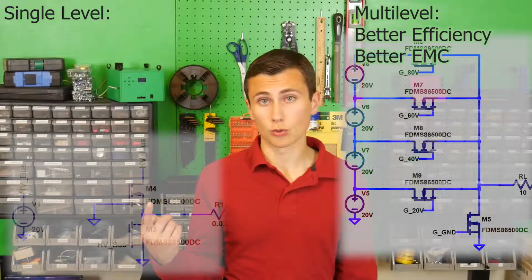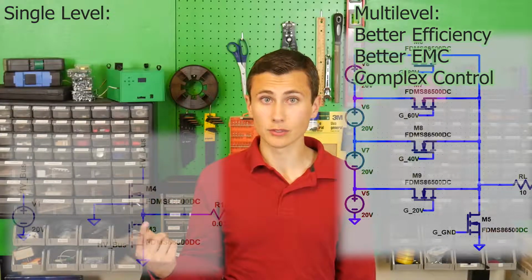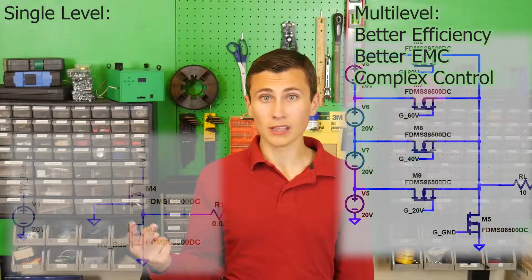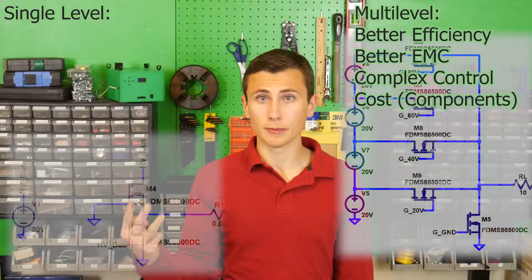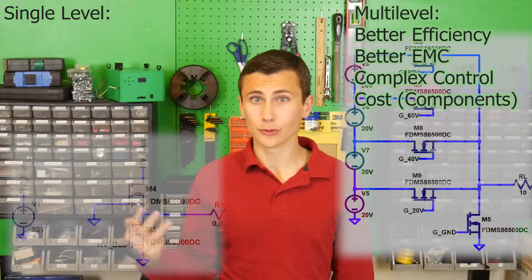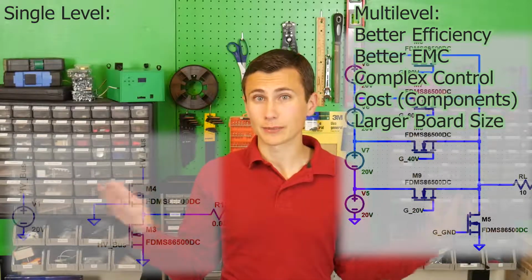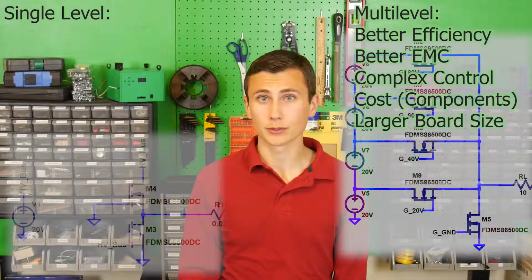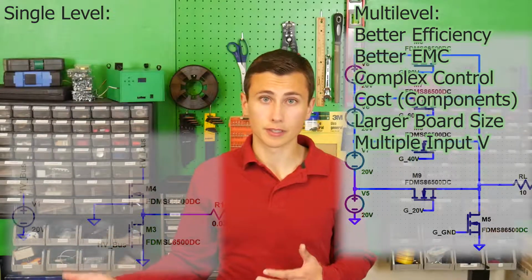First, a more complex control scheme, since you'll need at least one switch for each of those additional voltage levels used in your system. More switching elements capable of handling the currents at play, which increases the cost of your design. A need for more high current routing on the PCB is also introduced, and that'll directly increase the physical size of your board. Last but not least, you need to add a cell balancing circuit to maintain the voltage levels required for each inverter level across each leg of your capacitor bank, besides the added cost of the extra capacitors.